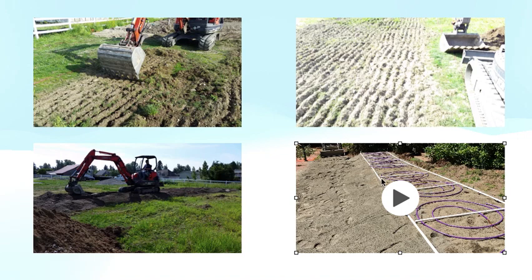So if this is your supply line to the left, let's say, in this case you have 2 coils connected together at one end, and then on either end you have a connection to the left and to the right. So long as that's consistent, whether water is coming from the right or to the left, water will still get to all these coils and still be able to flush. So whatever side this is on is irrelevant so long as you attach these coils correctly, and that'll be site-specific.